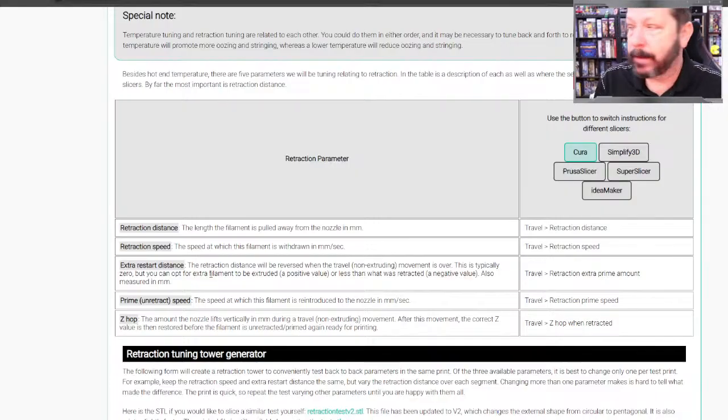But if it's the one that's cooling the heat sink, that one should be on all the time. So things that can happen when you're replacing stuff is it is possible to actually damage the fans or the wiring. Those wires are pretty small for the fans.